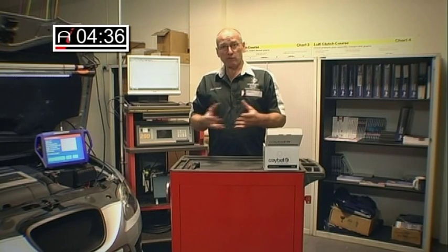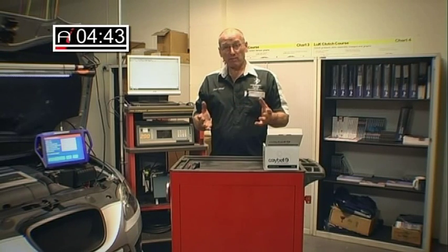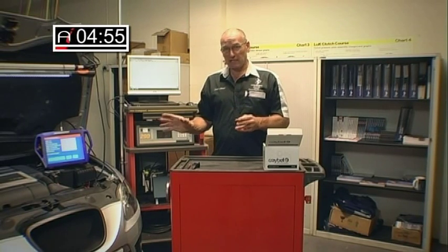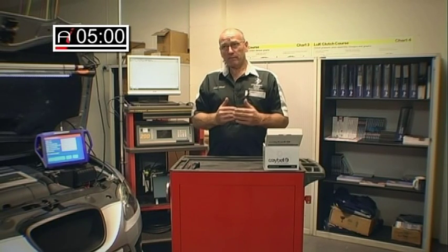Effectively what we're doing is drawing air into the engine illegally through an induction leak. It could also be affected by an exhaust leak as well. So there are many options why an air mass meter value could become incorrect. Another very obvious one, of course, is EGR. Where EGR systems are fitted, this particular vehicle does not have EGR. Where EGR is fitted, EGR is used to reduce the temperature in the combustion process by adding exhaust gas back into the intake.